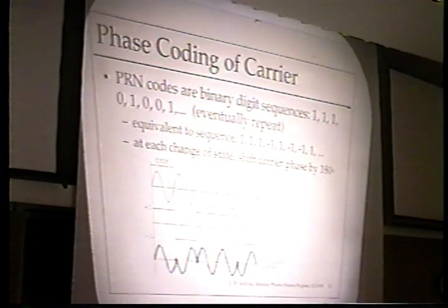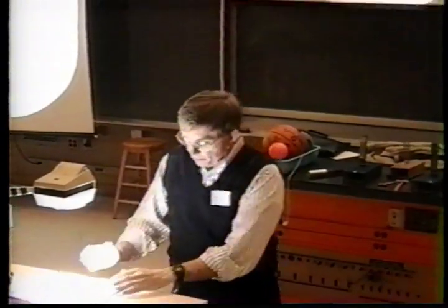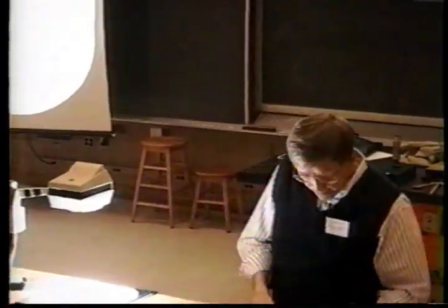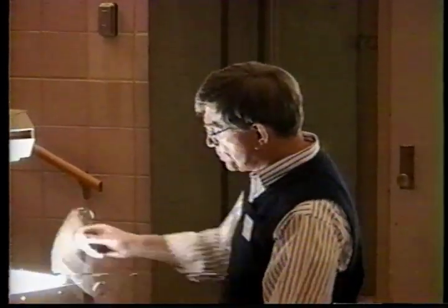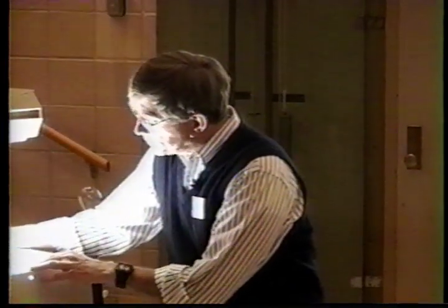Now there's nothing in the middle here. It's a couple ones in a row or something. So it does 2 cycles. And then hits another boundary. You either went from 0 to 1 or 1 to 0. And it flips again. It's easy to pick out these points. That's phase coding. You don't have to do great precision. It's easy to pick that out with electronics. And so that's how you decode or you get the information that's phase coded. It's a very robust way of coding.